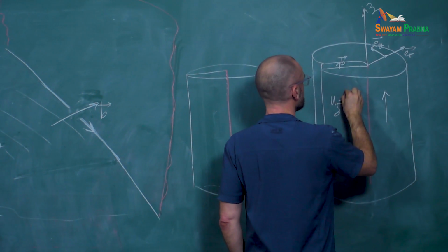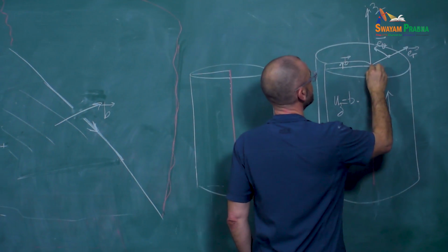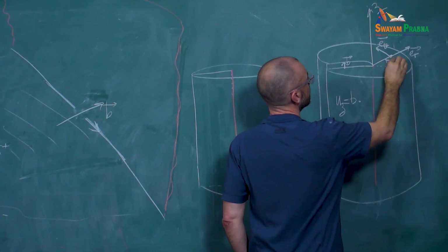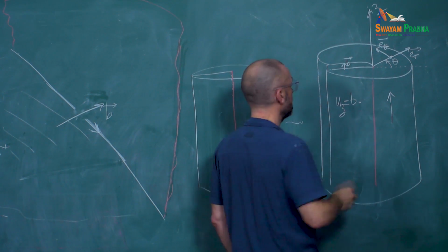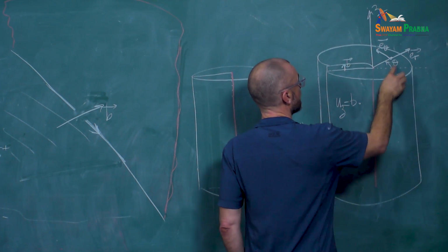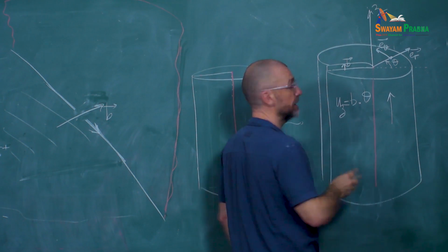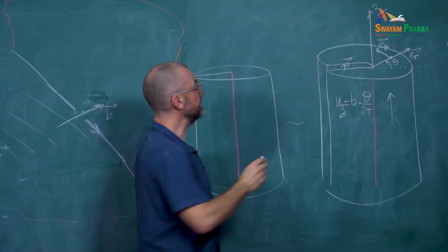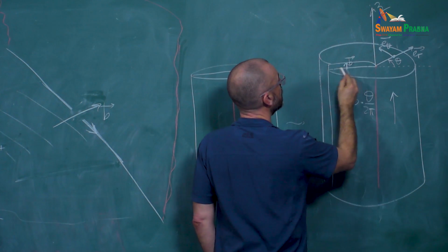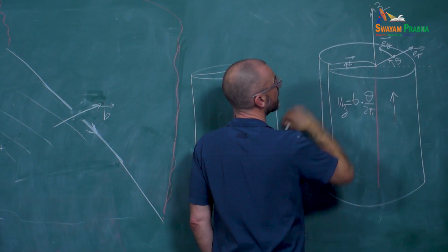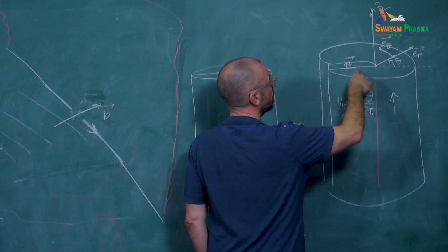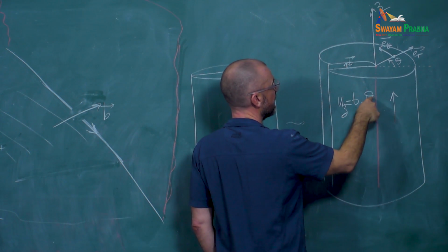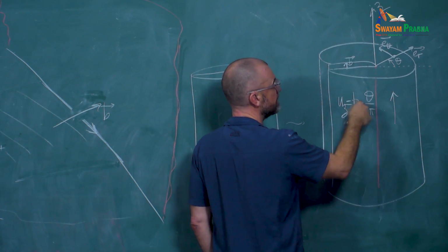And the expression of the displacement, UZ, is the Burgers vector B, and then if I take a reference line parallel here, I can define an angle theta, like so. And so it's going to be B times this angle theta divided by 2 pi. So it means that if I am along the surface on this side, then theta is equal to minus pi. So here I'm going to get B times minus pi over 2 pi. So that's going to be minus B over 2.